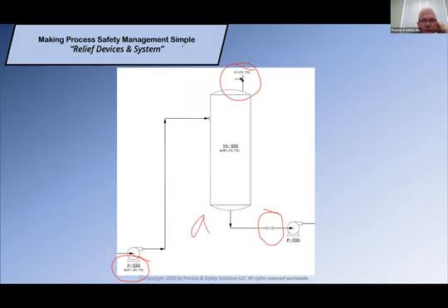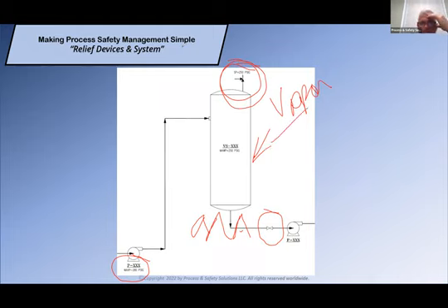So in a particular fire case, if I had a fire under here, I would be sizing this relief valve for that fire case and scenario. This would be relieving vapor or gas, depending on what's in here, but for the most part, let's assume vapor in a fire case. Now, if I'm also going to look at this scenario blocked in, this is all liquid. So rather than vapor at that relief valve, I've got liquid, right? So I have two different potential phases. Both of those would have to be looked at specifically, and I'd have to determine which one I have to address.